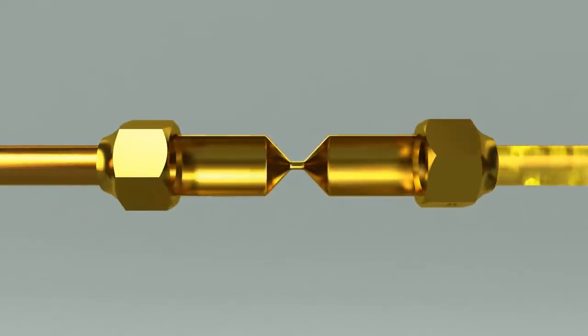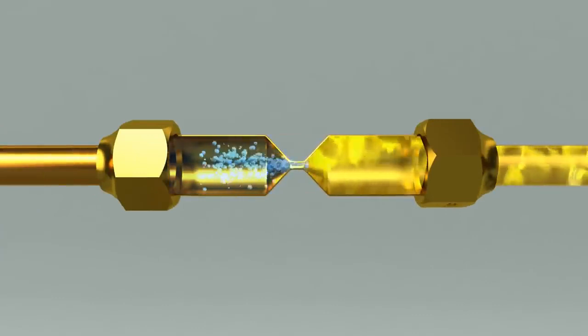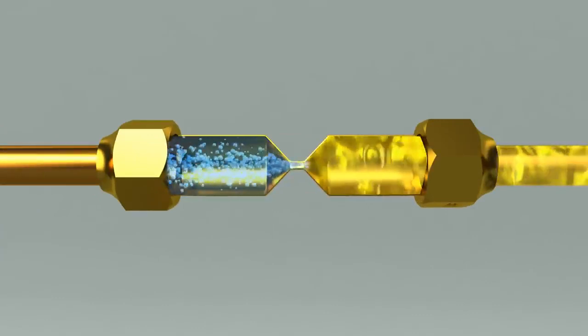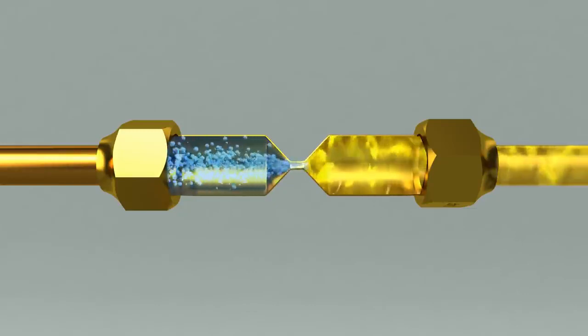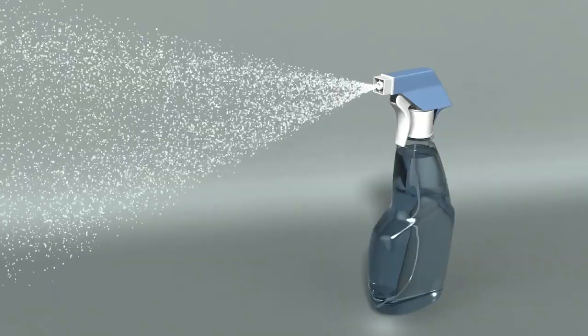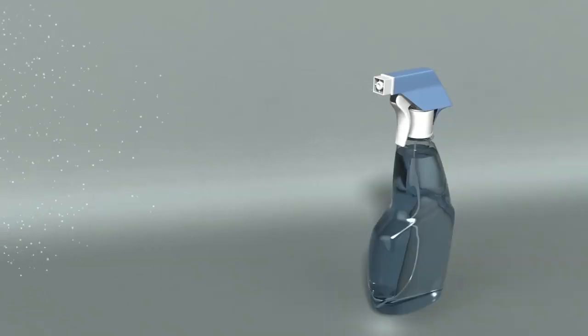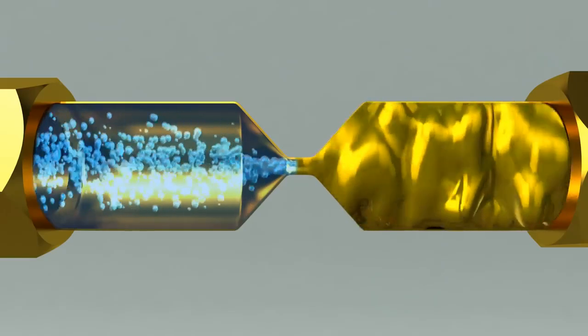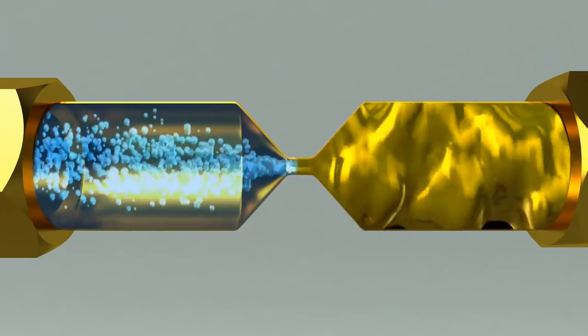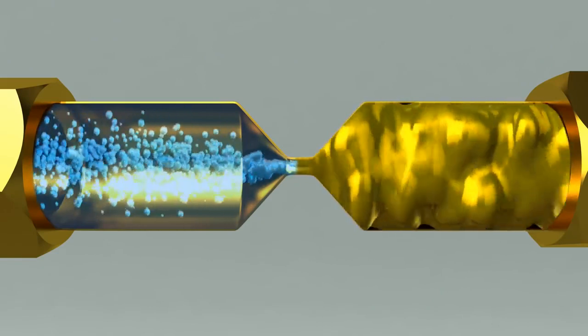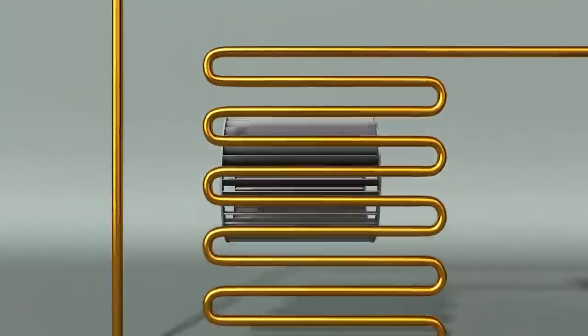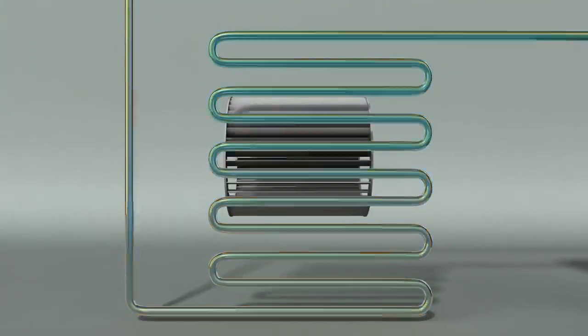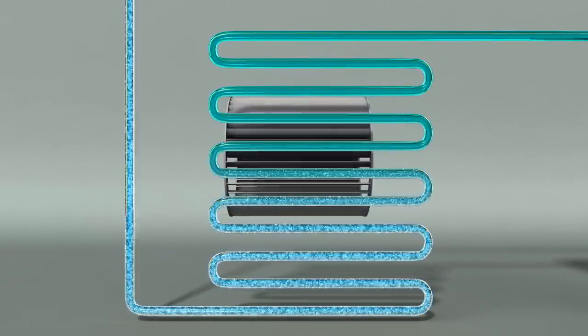The refrigerant passed through a condenser becomes liquid and flows into the expansion valve. There is a section in the expansion valve where the piping gets narrow, and as the refrigerant passes here, it splits up into many pieces. What we see here is similar to the principle behind water being spread from a spray. As the pressure on the refrigerant drops, its temperature drops dramatically as well. The refrigerant with lowered temperature then goes into an evaporator to steal away heat.